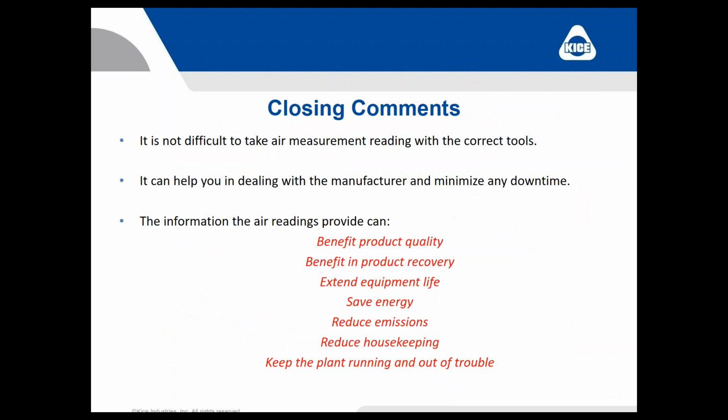Closing comments. It's not difficult to take the air measurements with the right tools. It'll help you when you call into Kice or anybody else and say, hey, my fan is doing this. This is my CFM. This is how I got it. It helps you minimize downtime, and the benefits are great. Product quality, product recovery, extended equipment life, energy, reduced emissions, reduced housekeeping, which is becoming more and more of an issue every day, and keeping plants running and out of trouble.